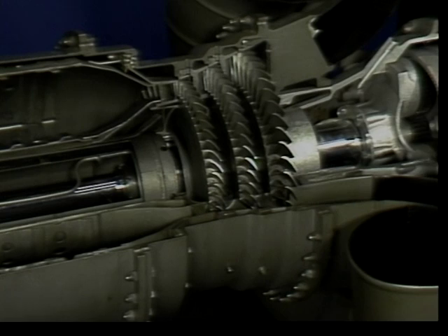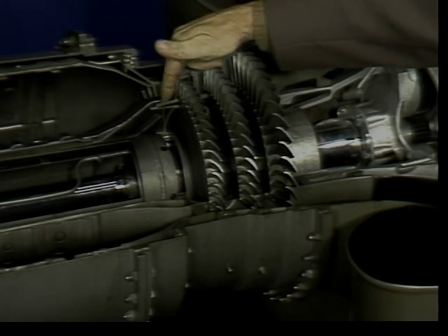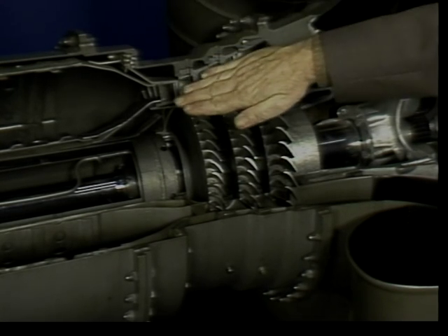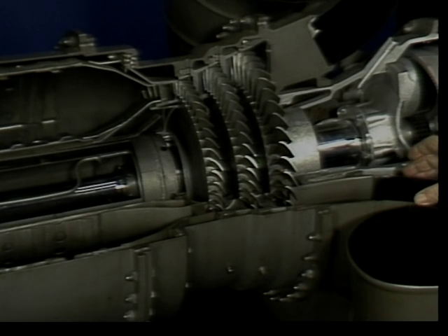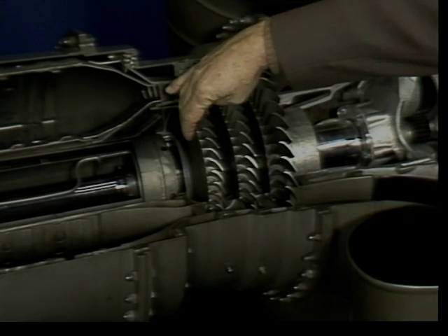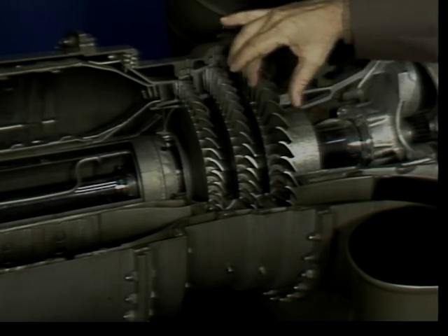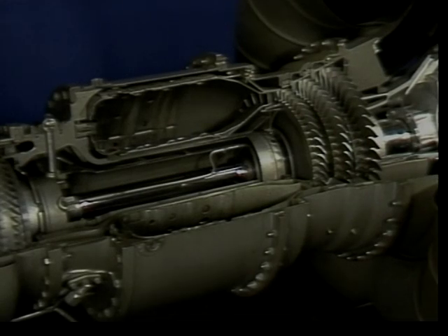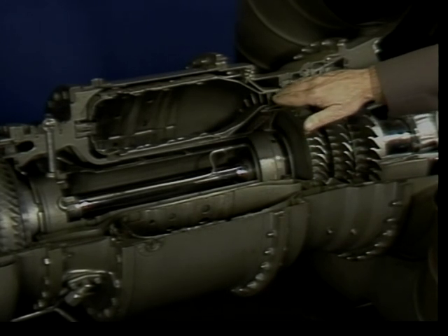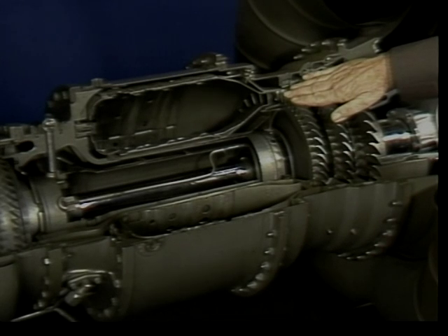Aft of the combustor, the turbine assembly consists of the turbine case, nozzles, a balanced rotor assembly, an exhaust diffuser assembly, and the turbine output shaft. The turbine rotor consists of 3 turbine rotor discs with blades attached to the turbine shaft. The turbine rotor assembly is where the hot gases from combustion are used to turn the shafts of the turbine and generator for sustained operation at constant speed.